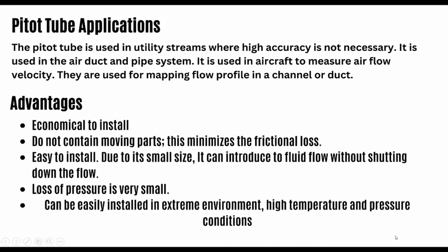And now pitot tube applications. The pitot tube is used in utility streams where high accuracy is not necessary. It is used in air duct and pipe systems. It is used in aircraft to measure airflow velocity. It is used for mapping flow profile in a channel or duct.